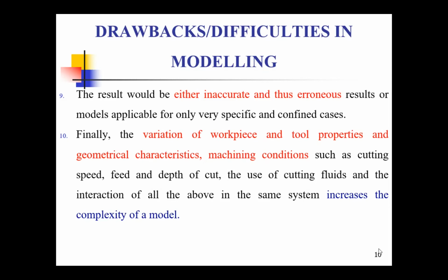If the cutting tool comes in contact with the matrix material, it removes the material easily. But when the cutting tool comes in contact with the reinforcing materials such as ceramics, silicon carbide, Al2O3, boron nitride, then the wear on the cutting tool will be higher. So in that case, more stresses or higher cutting forces will be developed.